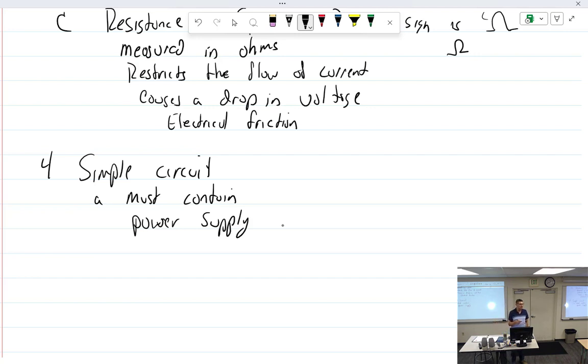Motor. Motor's the opposite. Alternator. What kind of electricity does an alternator produce? Technically, internally it produces three-phase AC converted in a solid state manner through diodes to direct current output, because diodes only allow flow of electricity in one direction, so it uses a rectifier. We could literally use something called a power supply, which would plug into the wall and produce power if we use our circuits, which we will be using here probably this week.